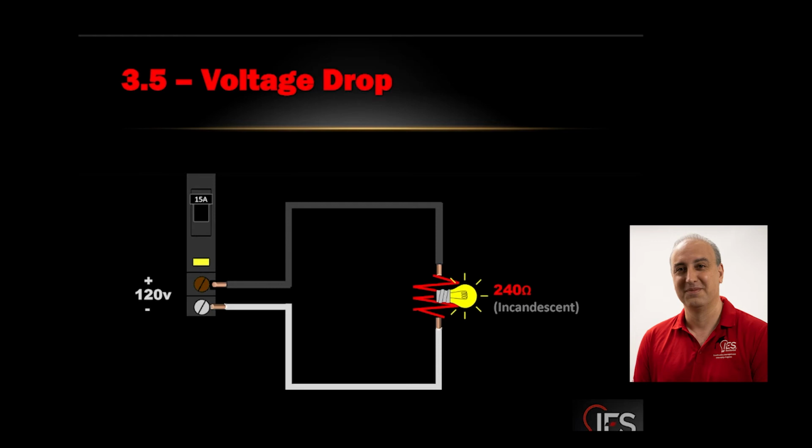This is a good point to talk about this. We've talked about AC, how this flipping happens, kind of like we don't turn a battery to generate. We saw that, right? It's usually a magnetic field that generates. But let's think about that battery because it's easy to remember. If I'm flipping that battery to generate AC, how fast I flip is what we call the system frequency. What's the frequency of our 240, 120, 240 here in the US? How many hertz? 60 hertz. That's telling us that we're flipping that battery 60 times per second. In Europe, it's 50. So with our AC, that direction is changing 60 times per second.